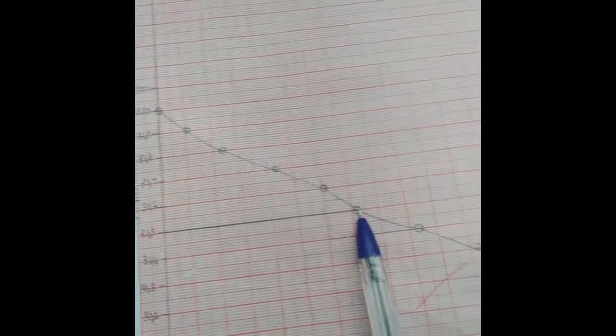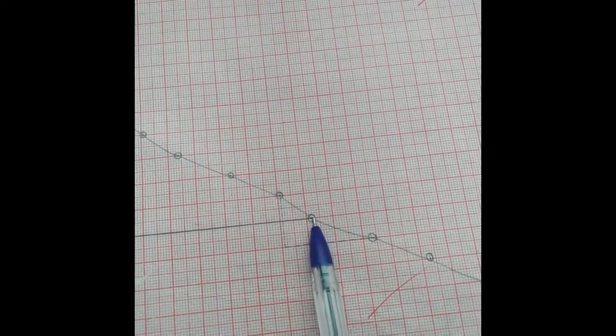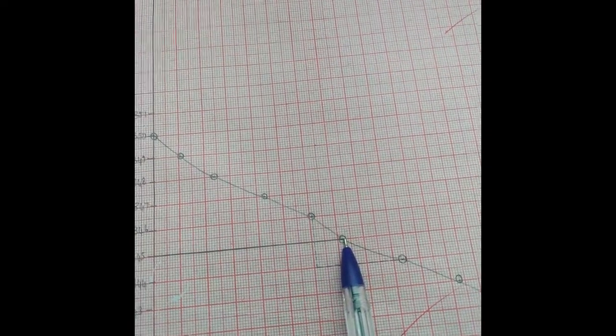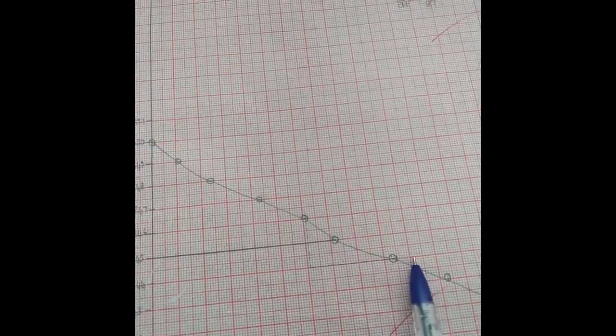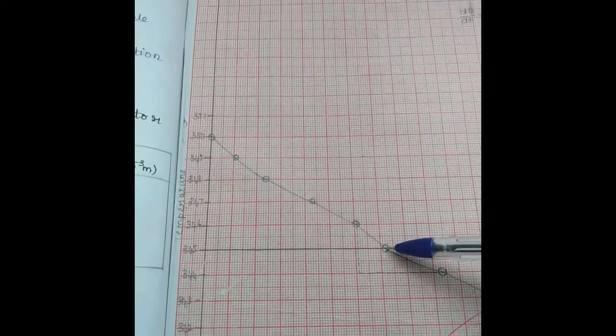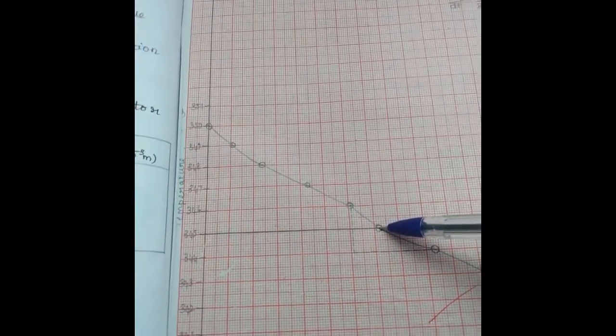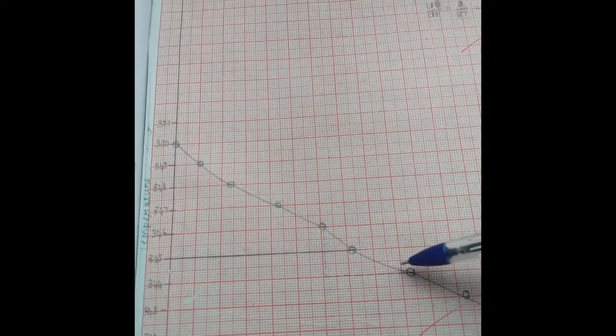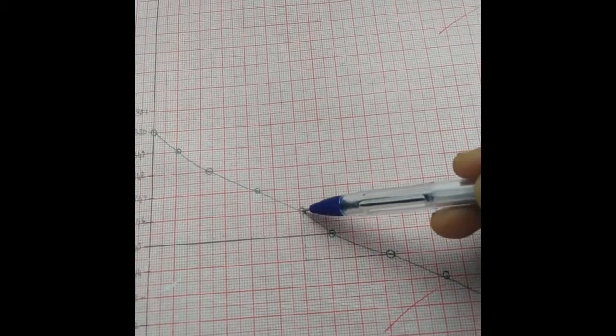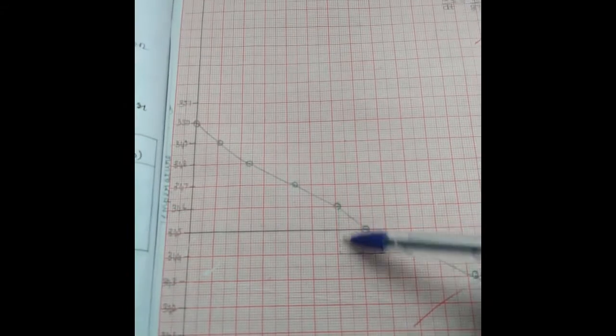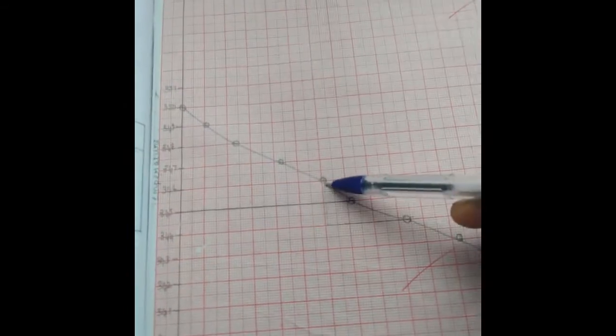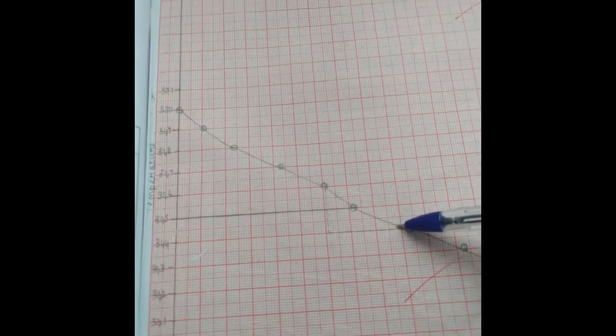You need to observe the slope. You need to calculate the slope between the points that lie just above the steady state point and just below the steady state point. This is the point that corresponds to the steady state temperature. You draw a line from the steady state temperature along the y-axis. Then you consider a point just above this point and just below this point. Now you need to calculate the slope between these 2 points. This will give you d theta. The temperature is represented by theta, so this represents d theta and this represents dt. So you can calculate the value of d theta by dt.